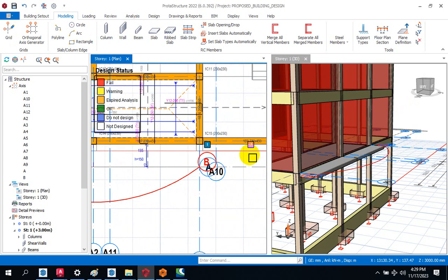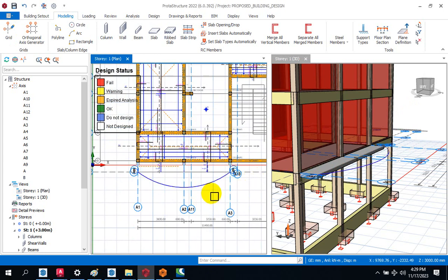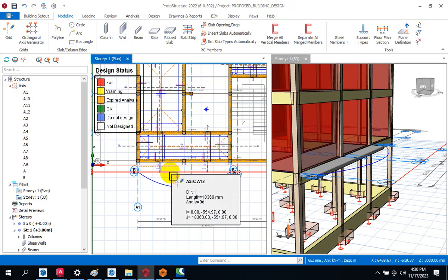So now it's okay. Because I was saying yesterday, the only way you can insert a slab, you must have 2 axes that are intersecting each other. At the point of intersection, that is the only place you can insert any structural member. So we must have this axis touching this other axis, have this grid here also touching this other grid here.